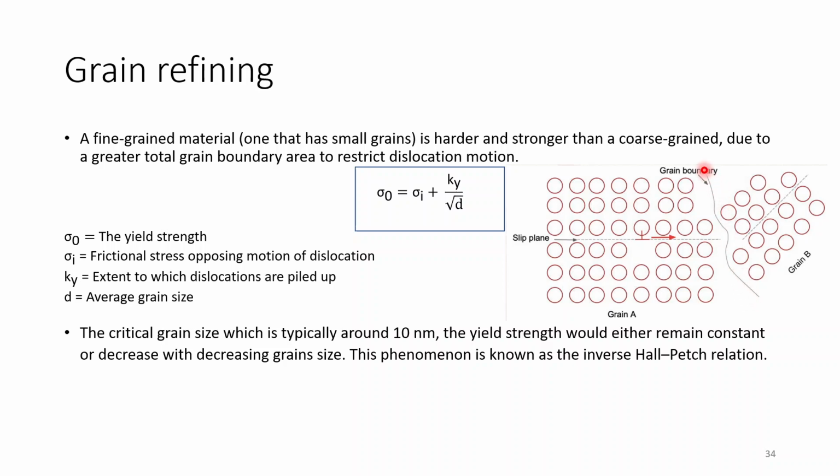Yeah, so in that case, if your material doesn't have these grain boundaries, what happens? Grain boundaries provide easy diffusion. So if your material has a lot of grain boundaries, diffusion will be very easy at higher temperatures and your material will be weak at higher temperature. In the case of turbine blades, they are used at high temperature and you require very little creep. So for good creep properties, you use single crystal type of structures. Okay, ma'am.